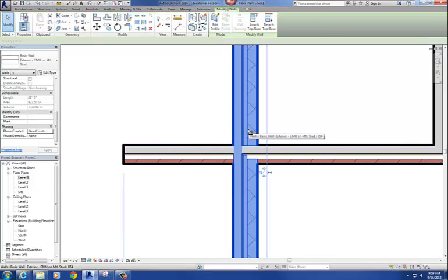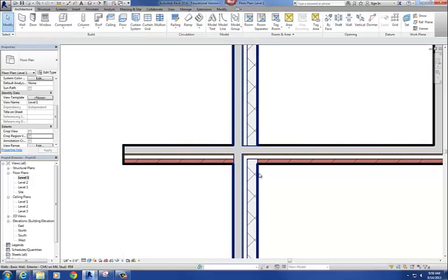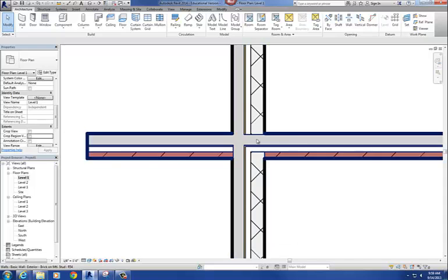All right, so what Revit wants to do with this is create as close to real-life conditions as possible when you have an intersection of a wall. It wants to show that intersection exactly how it would be built. When you're actually building this, the metal studs go in first, and then they're going to put the sheathing on. So obviously the sheathing from this wall can't cut through that sheathing. And then the sheathing from this wall is actually going to connect to the sheathing on that wall and turn the corner, and then the air barrier here is going to be continuous throughout the wall when you turn that corner, and then you're going to have a termination where the brick stops and the CMU starts. So that's what those layer functions are trying to do, create a real-life condition for the intersection of that wall.